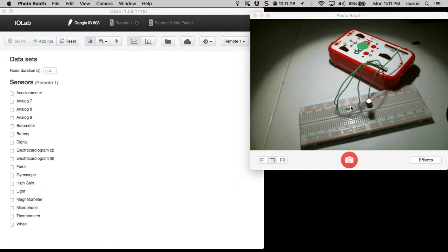The resistor capacitor pair consists of a 10K resistor and a 100 microfarad capacitor. I have the back end, the negative side of the 100 microfarad capacitor, hooked to ground. And now what I'm going to do is set up to take data. We're going to actually take the data, and then I'm going to do a curve fit for it to see what exactly the functions are for charging and discharging.